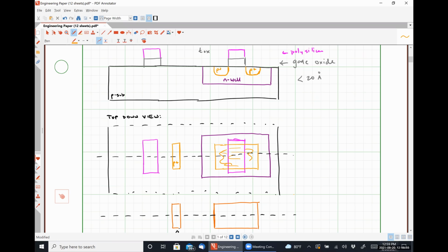The select layer tells the operator where to bombard with those acceptor ions. The active region tells where to cut a hole in the field oxide to allow that bombardment to happen. So they're so closely related. Again, most design programs treat it as if it's really just one mask. So we're going to call this active and select.